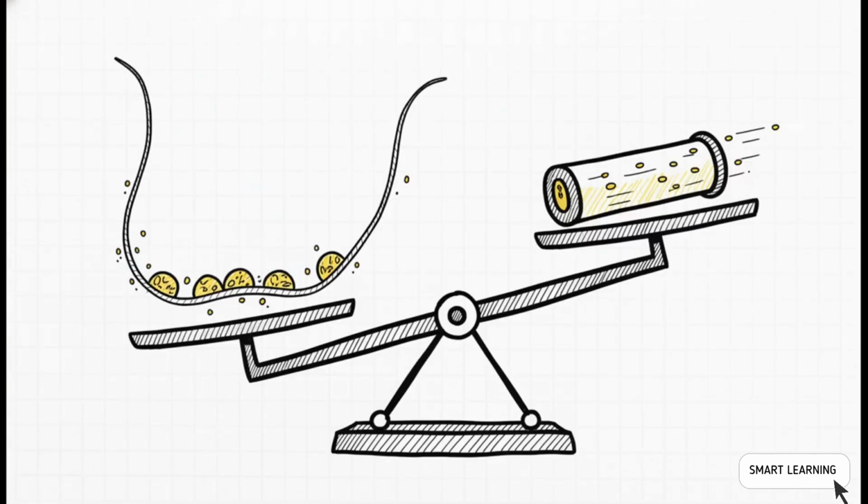And we can actually wrap all those physical factors up into one neat little mathematical package. R equals rho times L divided by A. Resistance equals the material's resistivity multiplied by the length of the wire divided by its cross-sectional area. The takeaway here is super intuitive. If you want to increase resistance, you make the wire longer or thinner. If you want to decrease it, make the wire shorter or thicker.